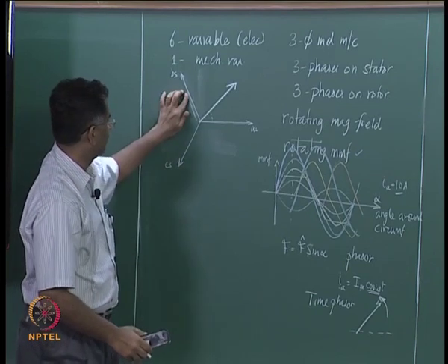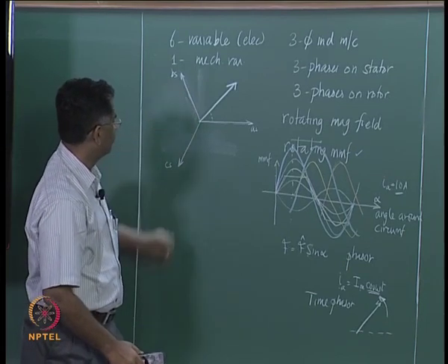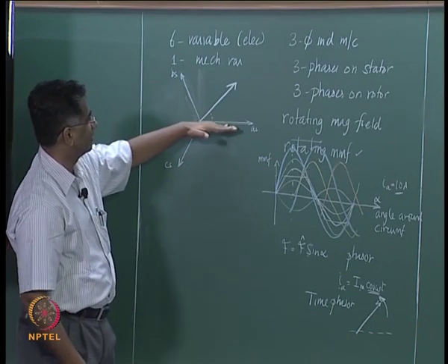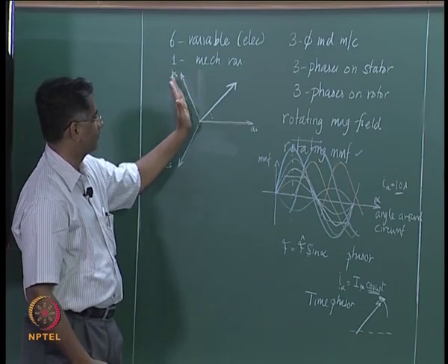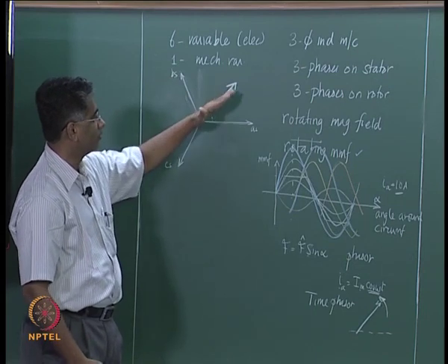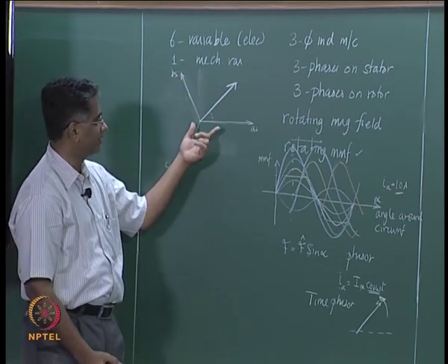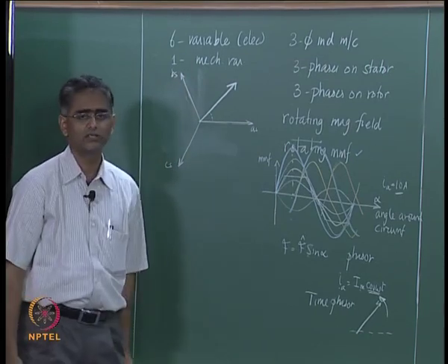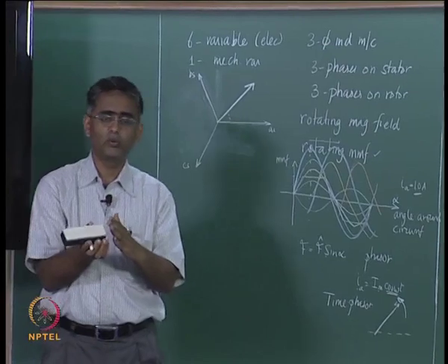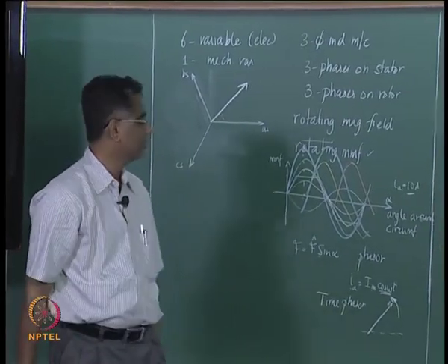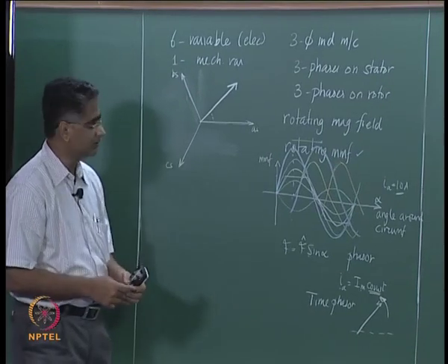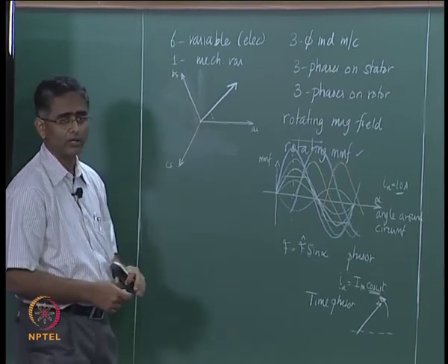You might also remember a few lectures back we had also demonstrated that the net MMF generated by these three could be rotating in space by considering excitation along this axis, that axis, and the other axis, and we saw that the net MMF is constant in amplitude but rotating. So, this is the net result, a phasor that is rotating in space.